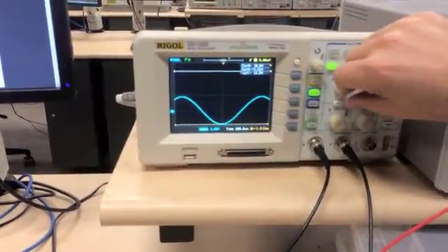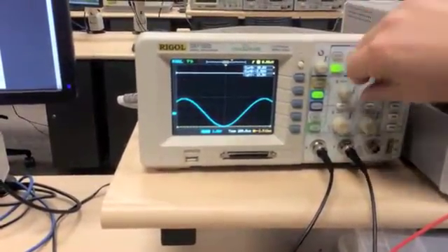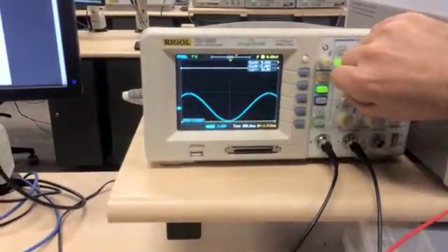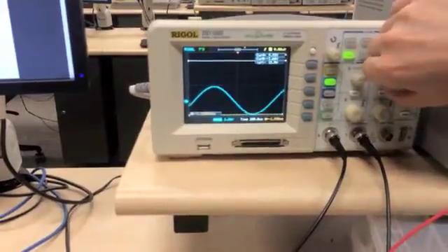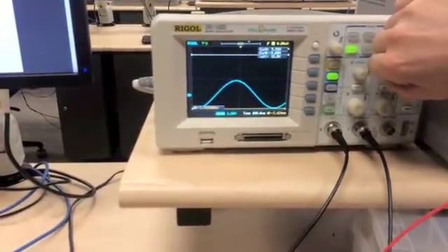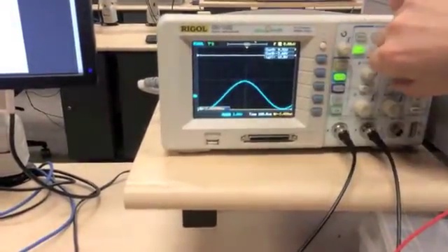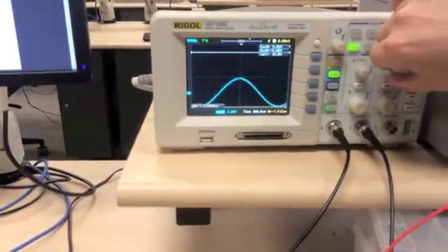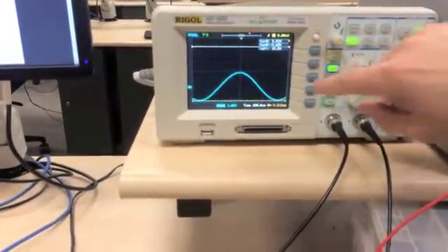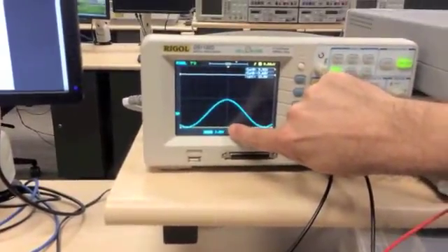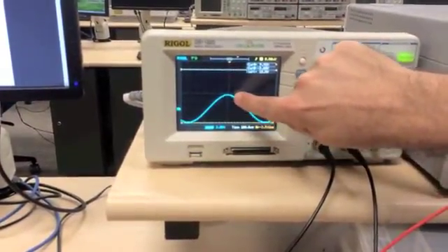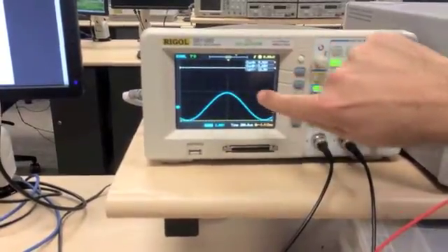So to measure the voltage peak to peak, I may vertically adjust my waveform to the bottom of the window, center it with the horizontal shift so that the peak is along my measuring axis, and then I can count divisions and multiply by the voltage per division. So I have a fractional or decimal number of divisions: 1 square, 2 squares, 3 squares, and then it looks like I have 4/5 of a square.